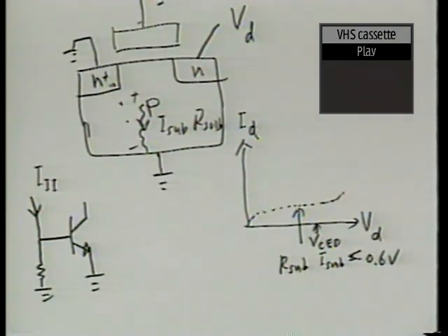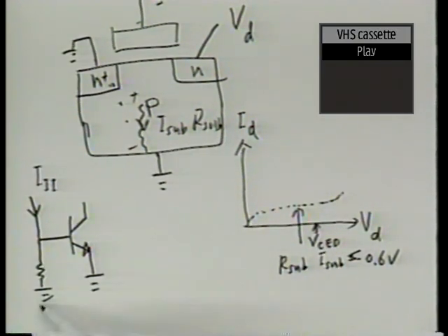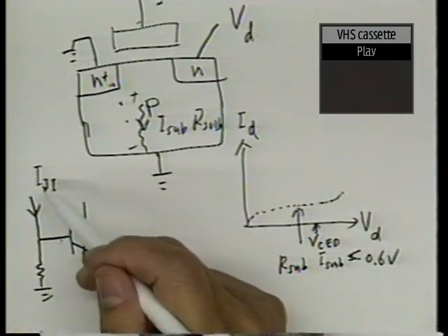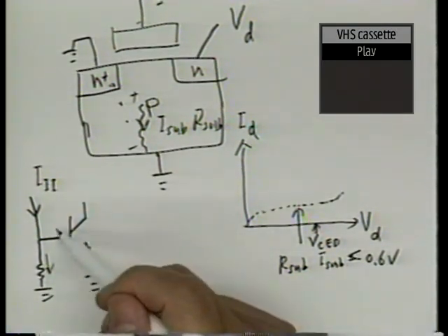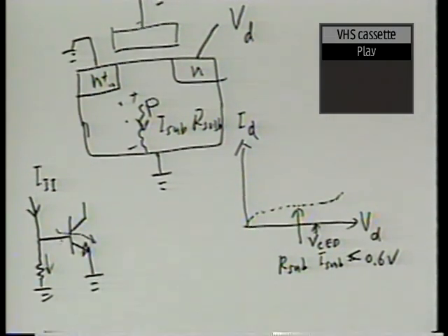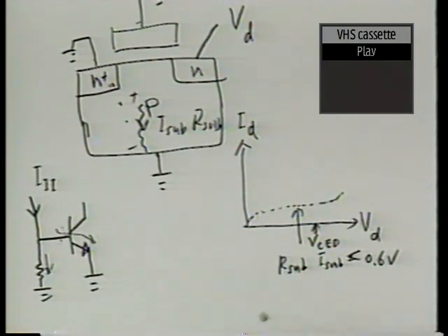Is that right? So as long as this impact ionization current is being drained away by the body contact, this bipolar transistor does not have any gain. Agreed? But why should the impact ionizing current prefer to go through this path rather than this path? If it goes through the second path, we're in trouble. Why should it prefer the first path rather than the second? Well, of course, simply because this is lower impedance than that transistor,